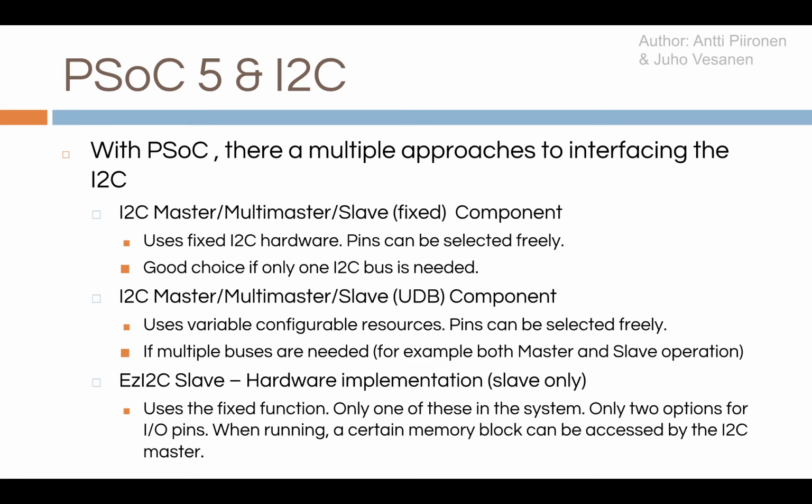Yeah, PSoC5 and I2C. On PSoC, there are practically 3 different approaches to interfacing I2C. There is I2C master, multi-master or slave. You select it from the component, either using fixed or UDB. With fixed, it uses the fixed I2C hardware, but the pins can still be selected freely. It's a good choice if only one I2C bus is needed.